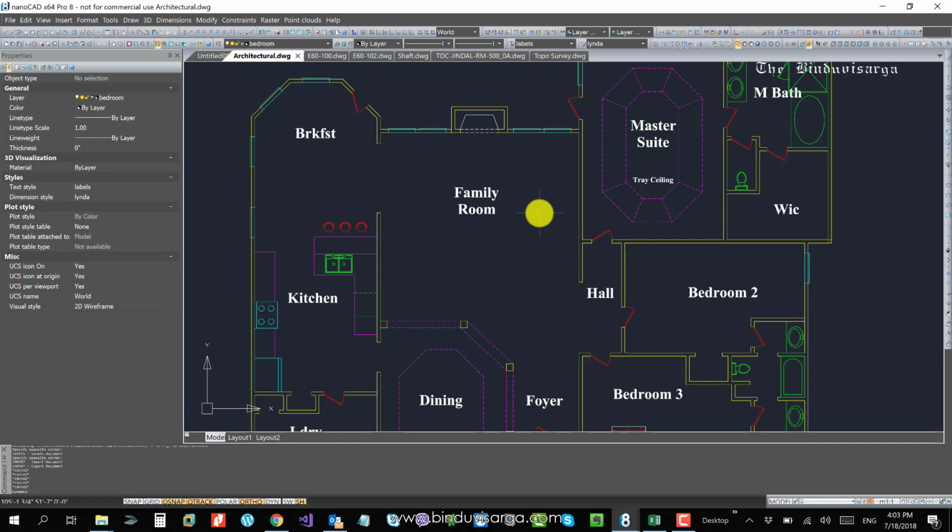So they may generate some proxy objects in the file. So it is mandatory that you are sending the correct DWG file to your clients, combining all the resources you had used in your file. To handle these situations in nanoCAD, we have a function called eTransmit.